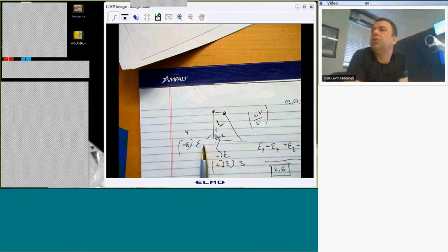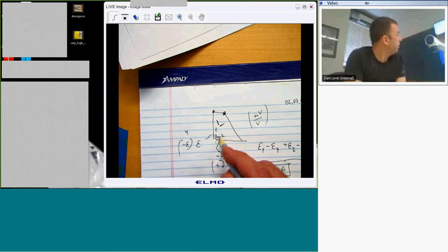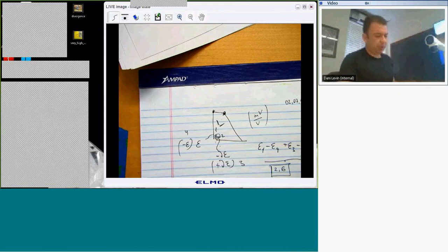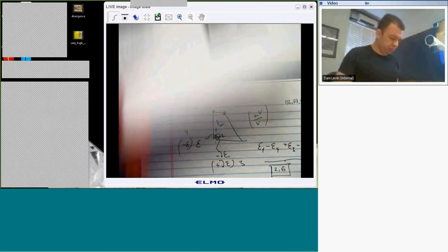You are talking about accelerometers? No, if we are measuring like 1 and 2, those are 90-degree apart. Okay. Yeah. So if we are measuring it separately, so from the values we can say that it is likely to be going pure bending, or it is going to torsion or something like that. For 1 and 2, or only here? Yeah, 1 and 2.